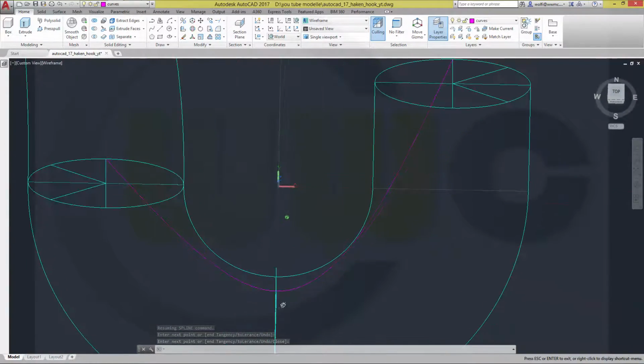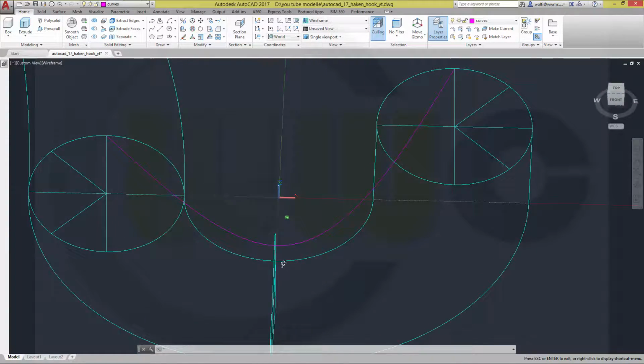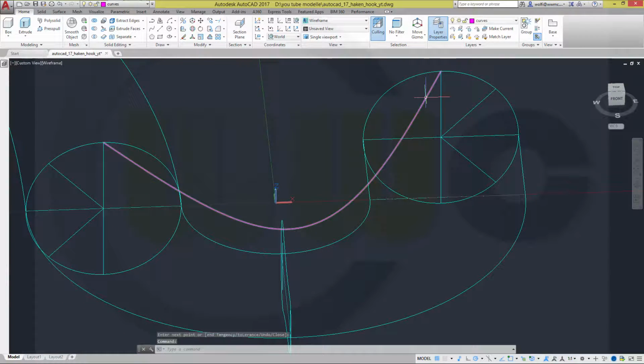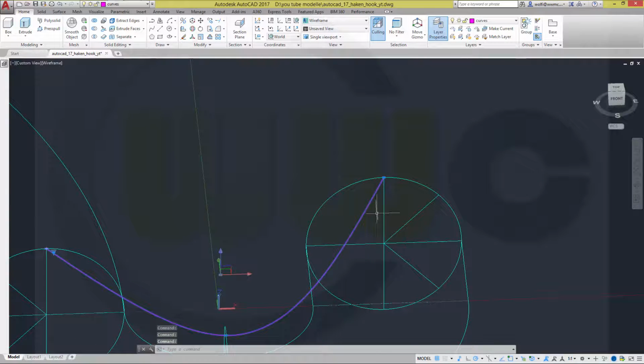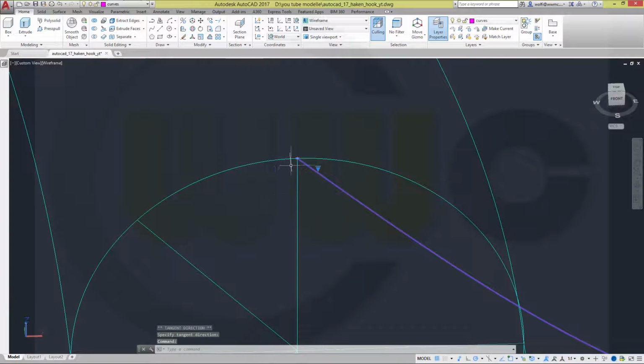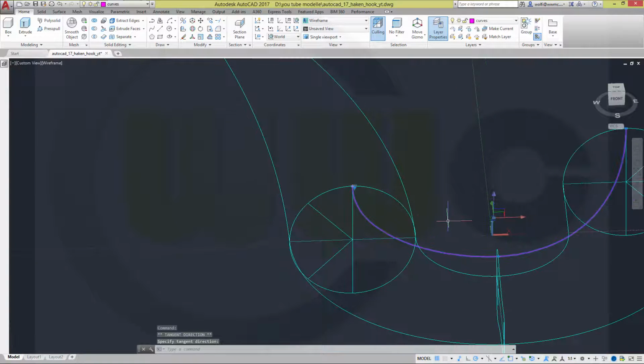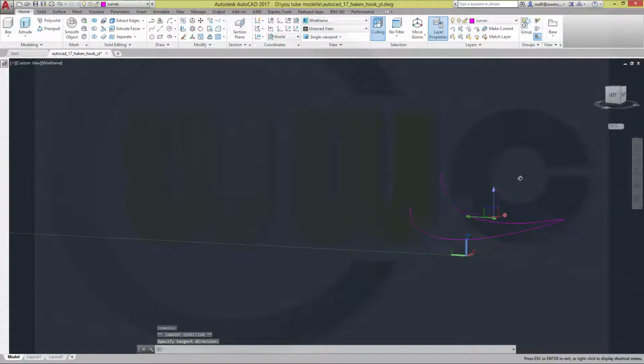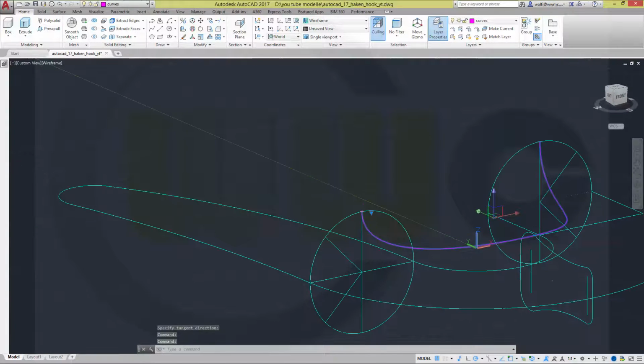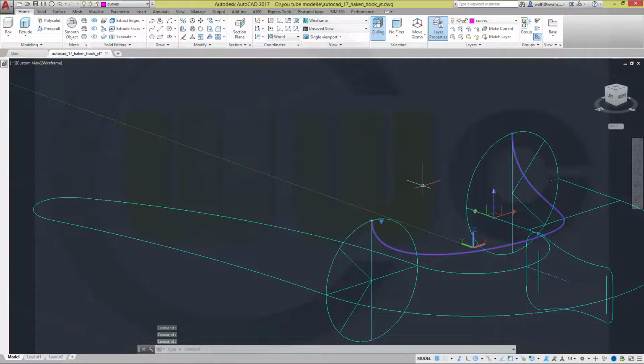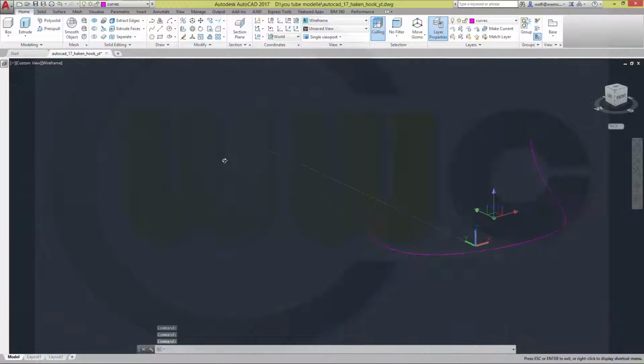And that's okay, yes. Go to the spline, go to the point and give it a tangent direction, and the polar snap is on, so this will work. Same over here. Tangent direction is this one. Okay. Looks pretty good, yes.